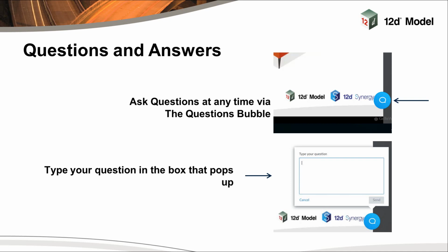So effectively the percent impervious value becomes somewhat irrelevant. And you just set it to 0 and you just use the pervious fraction there, and all your CP values will become C values effectively. So that's in a nutshell the way I would do that.